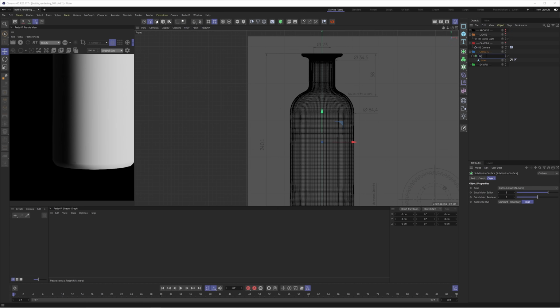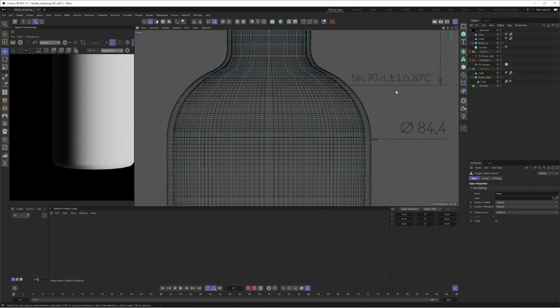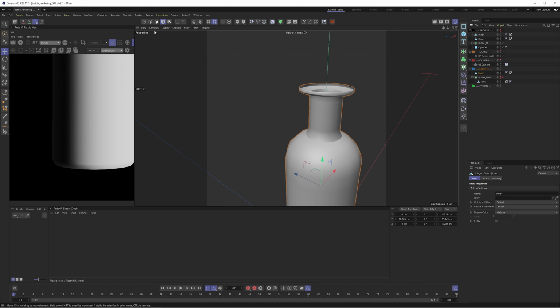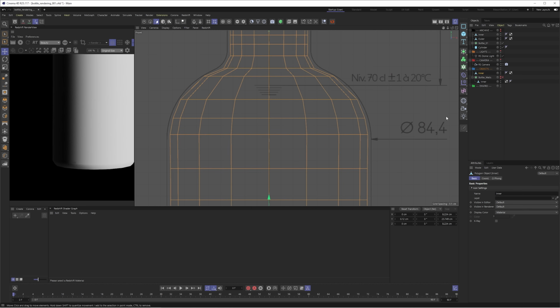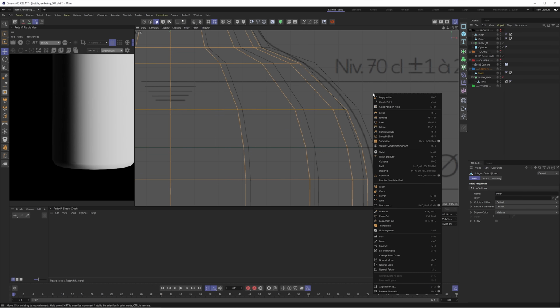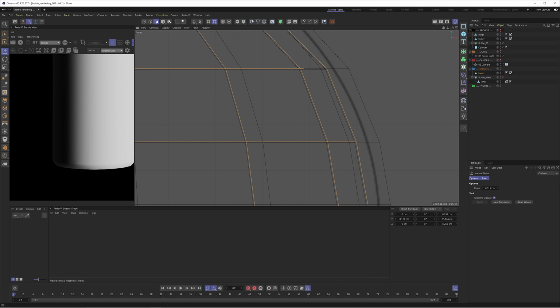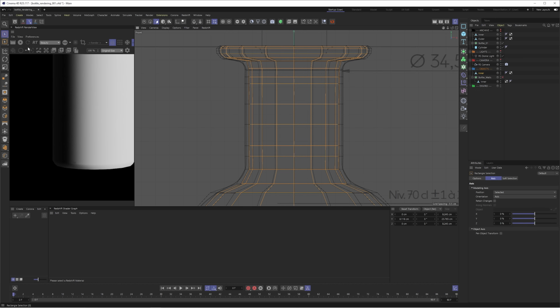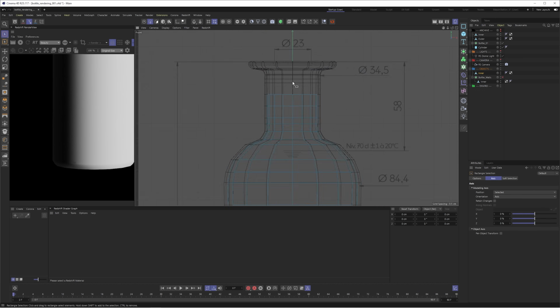Let's just quickly keep things organized and rename our layers. Let's take the inner wall we saved from earlier, and we're going to use this for the base shape of our liquid. In order for liquid to calculate properly, it needs to intersect the inner wall ever so slightly. We can do this by using the normal move tool from earlier to scale this up ever so slightly. We'll then grab the rectangle selection tool, go to edge mode and delete the top portion.